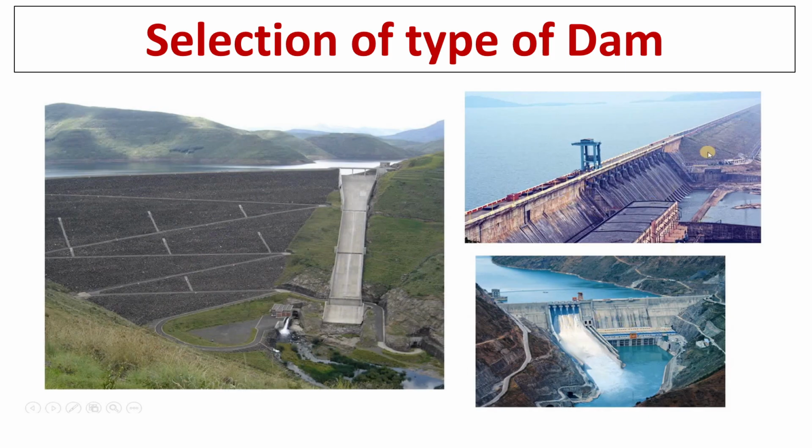We have seen different types of dams. We have fixed the spillway type. This is an important step. If the geology is poor, we have to go for an earthen dam. Further, if the dam length is more, we can also think of an earthen dam as it becomes cheaper compared to concrete. Further, if the spillway length is more and also if we have a dam toe powerhouse as shown in the right bottom image, we have to go for concrete dams.